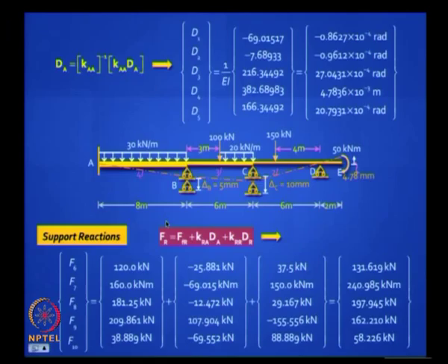You have got the active displacement, next step, support reactions. Take the second equilibrium equation, this is where your fixed end force vector comes in. Remember FFR, which you calculated and stored, and you have KRA dA and you have KRR dr, multiply them out, you have these end moments. Any doubt?